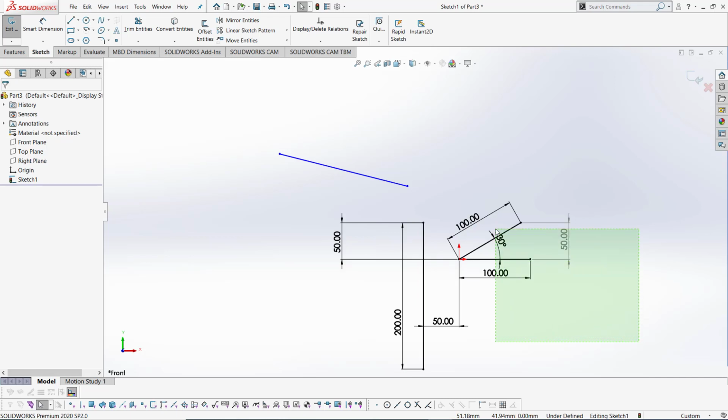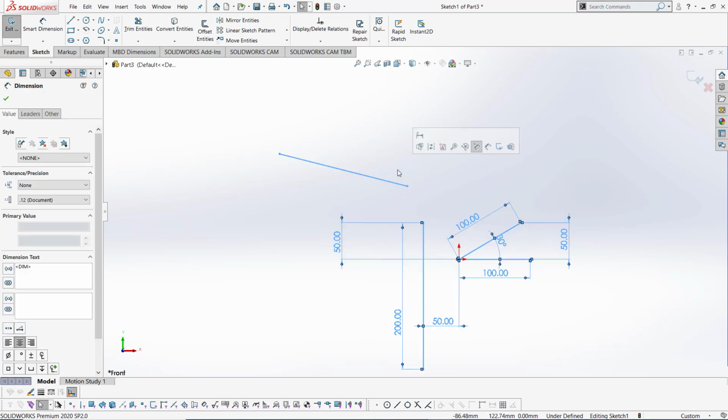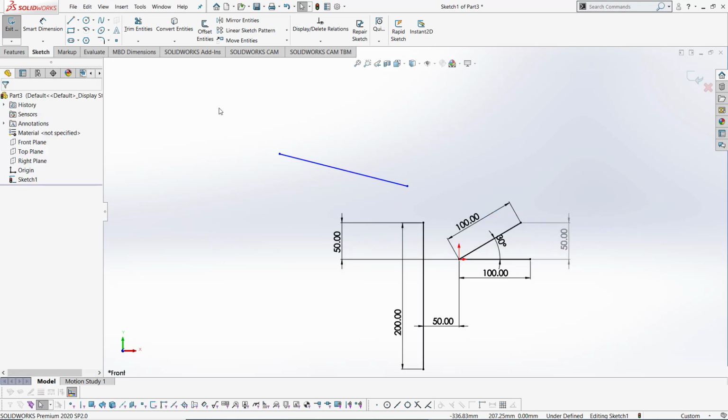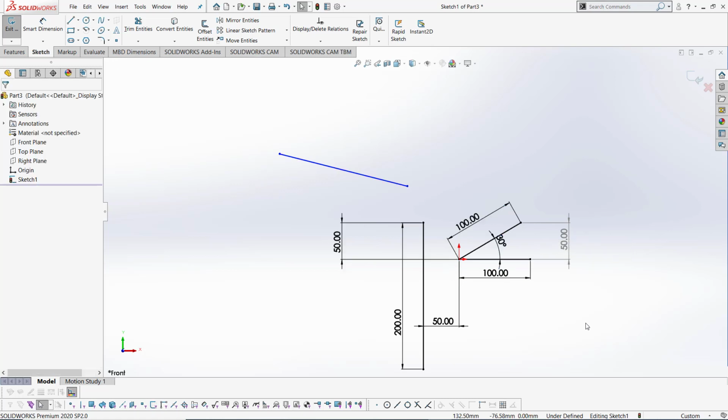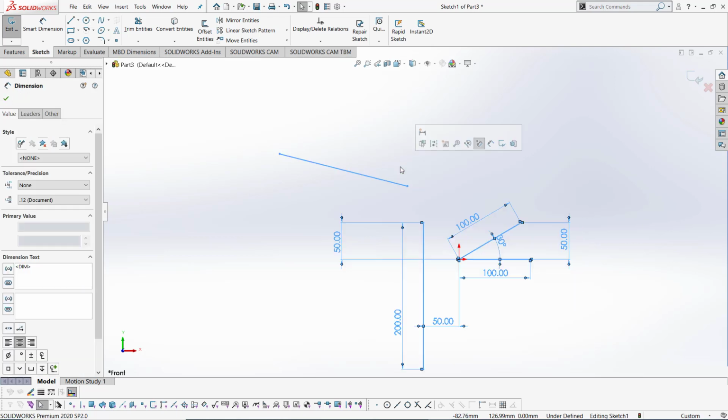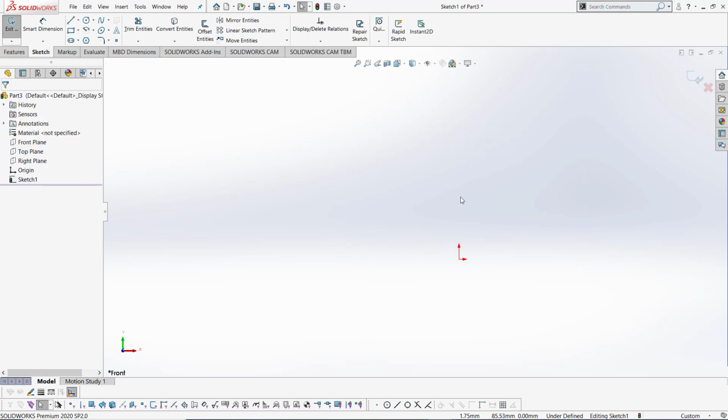So I am just able to select from the right hand all the way and just cut some of the lines, and this would enforce to highlight everything. Let's do that once again. If I select from the left hand and I just touch somewhere all the lines, it will ignore the lines that was not fully covered. But if I highlight from the right, if I'm just able to touch all of the lines, it will select everything that I have touched. Let's now hit delete on the keyboard.